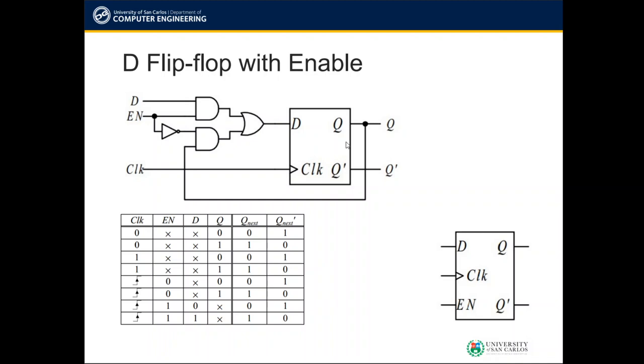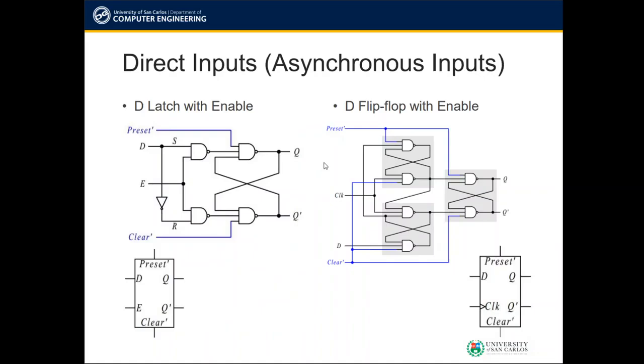Again, we are now in synchronous or sequential circuits. The outputs of your D flip-flop are synchronous to the clock, depending on the characteristic of your flip-flop, either positive edge or negative edge clock cycle. But the asynchronous inputs are additional inputs to your IC here.